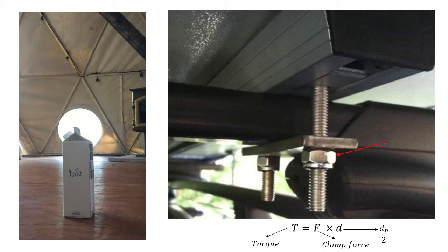So just by knowing the screw size and specs information, you can have information about the maximum torque or clamping force the cap or the fastener hardware can provide without getting broken. If you torque more, you'll get more clamp force. That means if the screw has 2 times larger diameter, you'll get 2 times the torque, and thus the holding downward force would be higher. We can always torque more to ensure that the force to clamp down and unclamp your system is high enough. That way your system is resistant against external vibrations and your bolt can still take a majority of the loads. So the torque you need to disassemble your screw and nut depends on the existing holding torque.